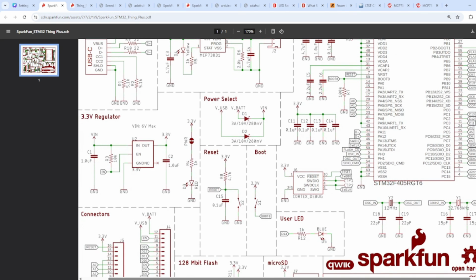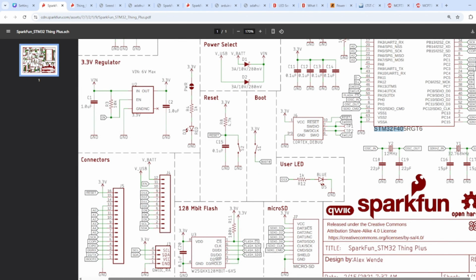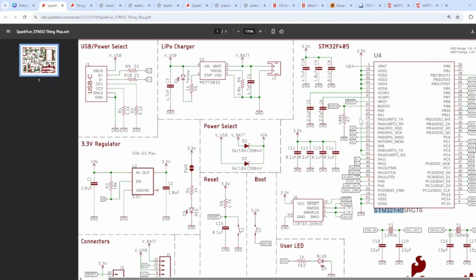So this is from the ST microcontroller STM32F405. Here you have the boot pin and a switch. The moment you press the switch, this will get pulled up. As a default, this BOOT0 pin is pulled down, which means there is a resistor connected and it has been grounded.